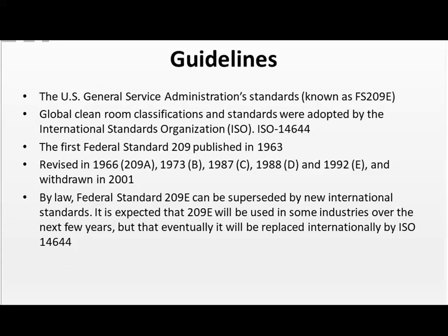We still talk in terms of the FDA standard as far as class 100, class 100,000, but the ISO standards are A, B, C, D, and they're similar, and you can see how they correspond. As I said, class 100 is a class A in an ISO standard. The ISO standards, though, the specifications is what is typically being used, and those specifications that we have gone through in this webinar are from ISO standards, and you can look those up and find those online.